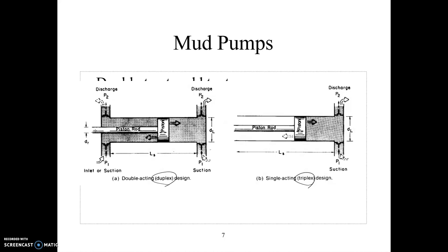When you do a forward stroke of each piston, the volume that is being displaced is basically the whole volume of this cylinder. It's pi over 4 dl squared multiplied by the length, which is ls. So this is one movement, one forward stroke, as we call it.